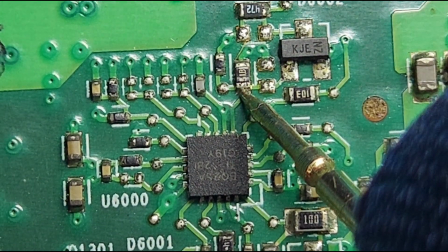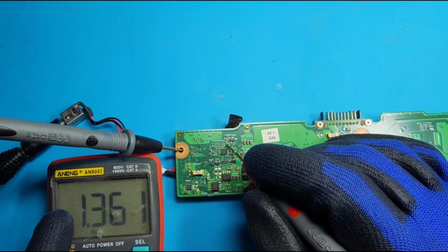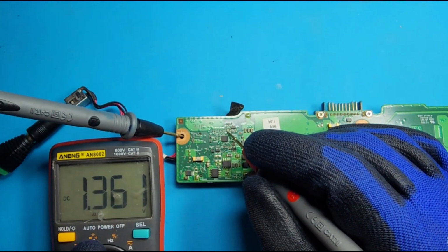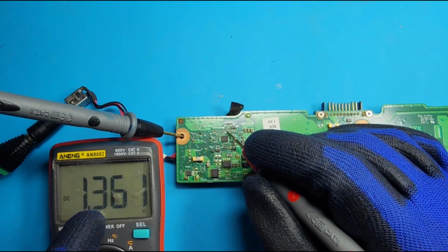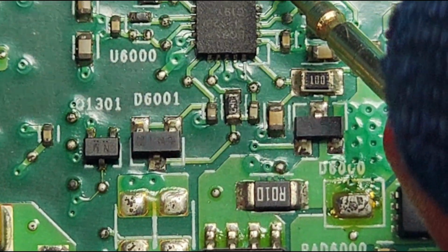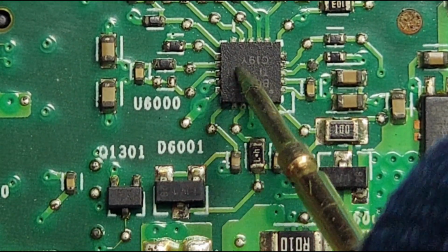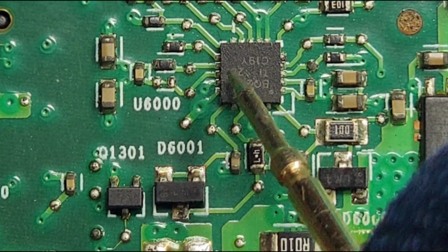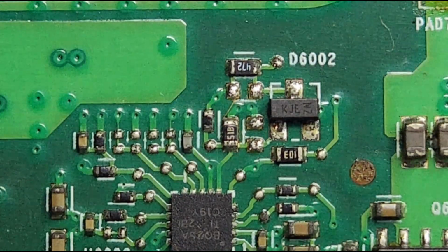So on this pin, if you look at the voltage, here we have 1.3 volt. The range should be within 2.4 to 3.15 volt. So 1.3 is not appropriate. If we have 1.3 on pin number 6, then the charger IC will sense that the adapter is not valid and it will not send the AC drive voltage as 24 volt on the AC drive pin. So this is the problem here.